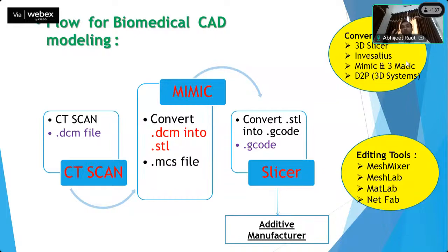While taking the input, it is also scanning the other areas. In industry, people call this noise, meaning unnecessary or unwanted area, which gets converted into the STL. So that's why we can't go directly to 3D printing.